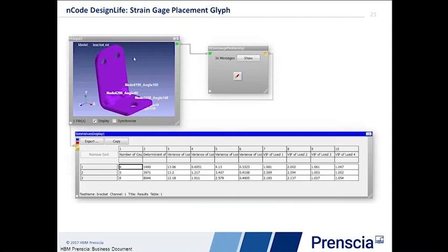And this is actually very important. If you miss a load, you're not going to generate a valid set of load estimates, because we've taken strain responses from the structure that came from a load that was never included. So the key aspect of this is, one, to have a load case representing every load going into my structure. Secondly, we identify locations where we can't put gauges. On almost any part, I'm going to have places that are covered up because of clamping, fixturing, bolts, things like that. So we identify places we can't put gauges.